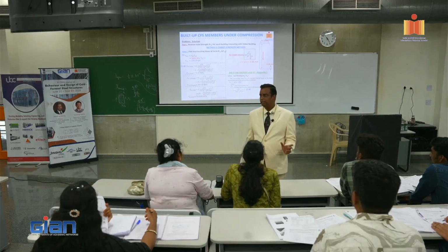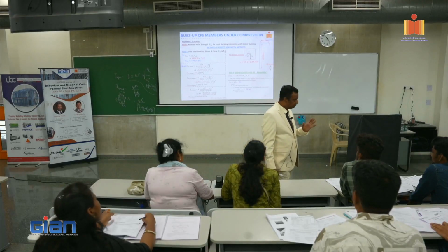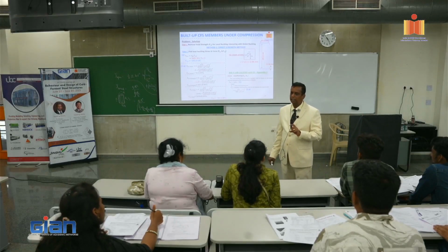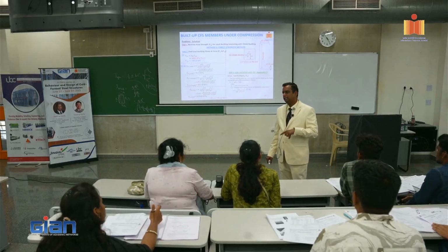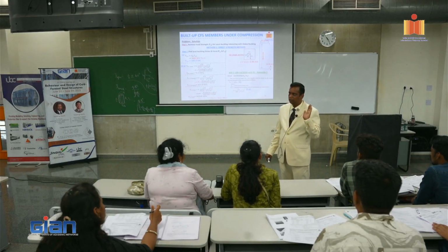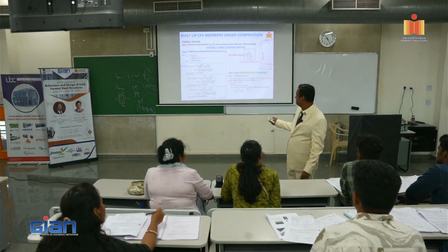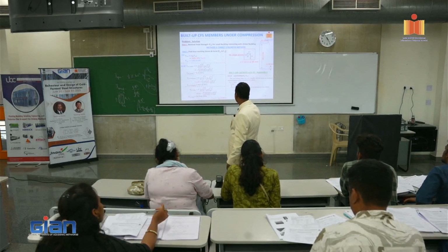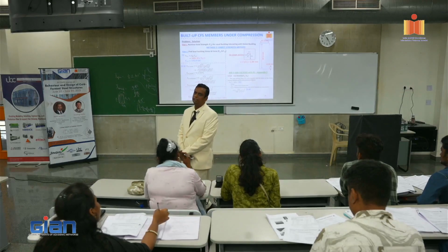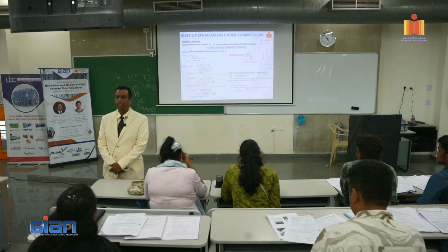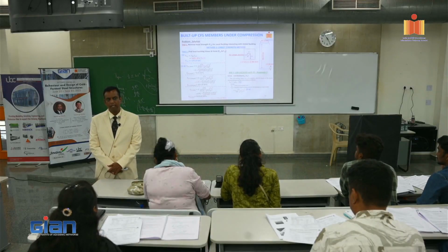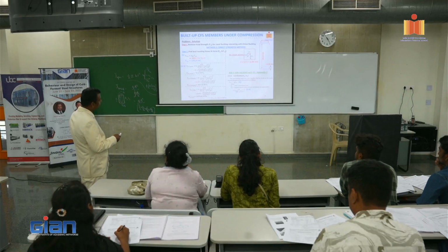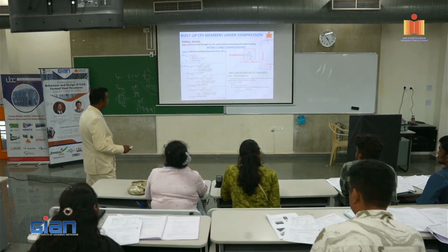So in the effective width method, we are finding out the sections that are effective, multiplying by the nominal strength. And in DSM, we don't reduce the area, we take the A gross and multiply by this FCRL and you get this one. That is the difference: in one place you are actually reducing the area and keeping the stress very high. In another place you are keeping the area and instead of Fn you are putting FCRL.